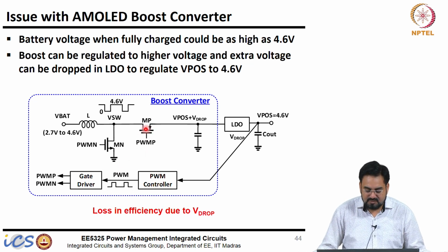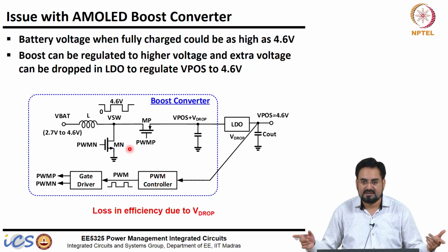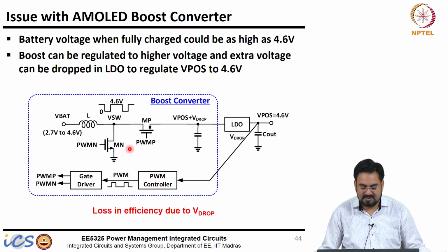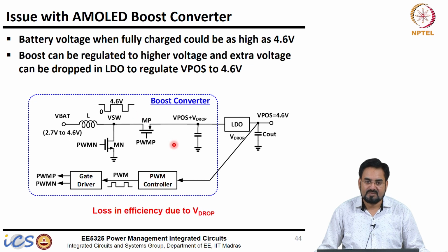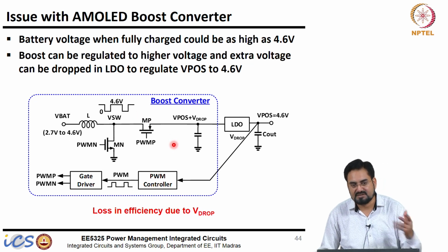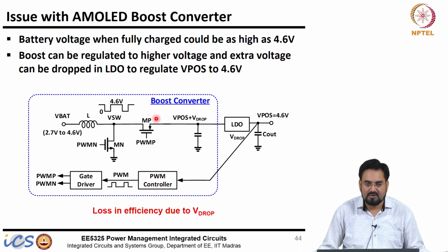So what we can do, when voltage Vin is very high and we know that it is going out of regulation, or your duty cycle is saturated to near 0%, is fully turn off this MOSFET and it will conduct through the body diode. It will basically enter non-synchronous mode and the drop will be more.